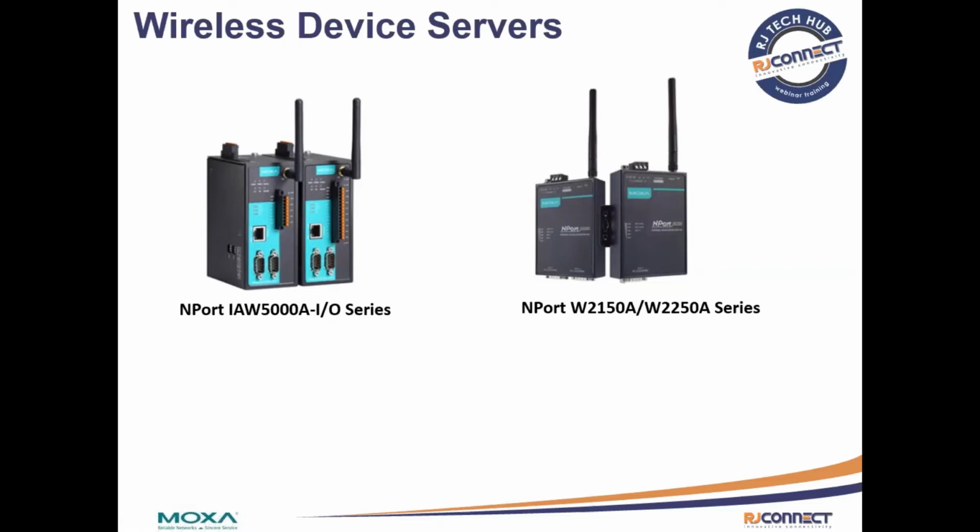and IEEE 802.11abgn, which is wireless. It's a wireless device server with 6 or 12 built-in digital I/Os. This device provides you with maximum flexibility when you need to integrate serial equipment in the field with an Ethernet network or cloud platforms. The combination of digital input and output makes this device server well suited for a variety of industrial data acquisition applications. The digital input and output on the device can be controlled over TCP/IP using the Modbus TCP protocol and can be configured and secured from the web browser.